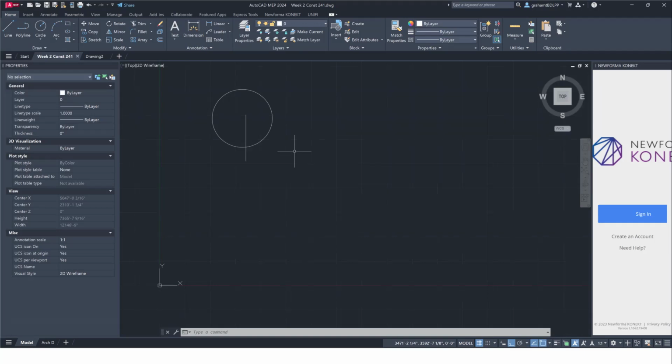We'll save that template and then we'll utilize it again. But we're saving the settings. We're not necessarily saving the content that's on it. We're opening up the DWT, we're working on the DWT, and then we're saving it to DWT. No. Close. So we're creating a new DWG by using the DWT. So you should never be drawing in something that says DWT at the top of your screen. If you are, you're drawing in the template. Okay?